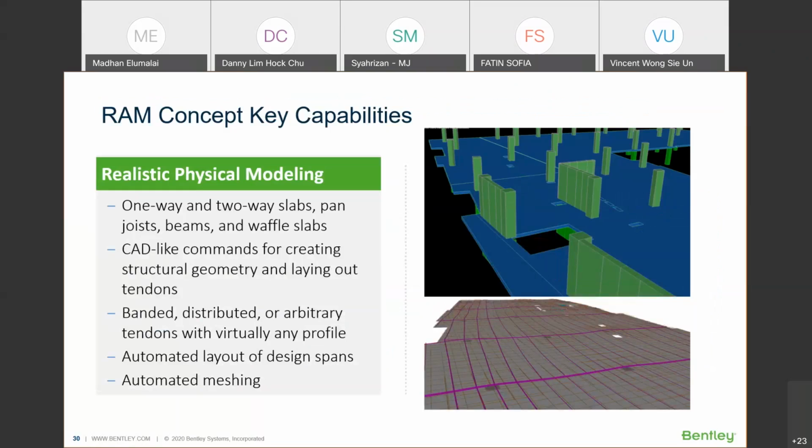And the modeling is extremely user-friendly. You can import the CAD drawing from any CAD software, and you can trace over it the floor drawing to create this finite element model. This is a floor design program, so you can model only one floor at a time. You can analyze only one floor per file.